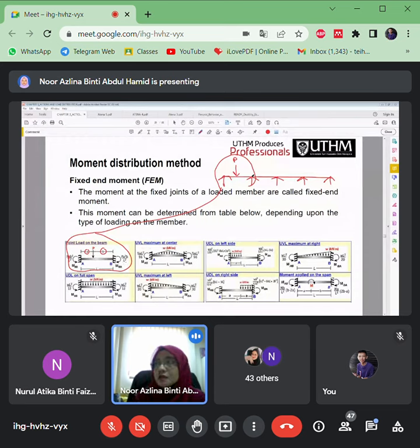For the second span, it has a uniform load, so for all of these uniform loads, you still need to analyze span by span. For these spans, you have to use this equation: WL power of 2 divided by 12. Also estimate it for this one and for these spans according to the load.